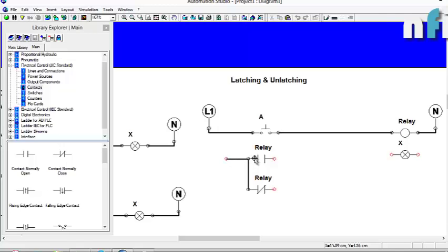Okay, so I was talking about the latching. So I'm going to give this line neutral. Oh, sorry, this supply I'm going to give it a live. This is common. All right. So let me just write here once. This is common. This is NO. This one is NC. So this common is connected to line, and this NO is connected to a terminal which you want to latch. Sorry, it is connected like this. So I'm connecting this NO terminal to the switch. NC, this is left alone. I don't want this NC here. So this connection is called latching.